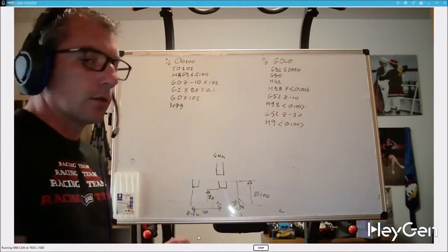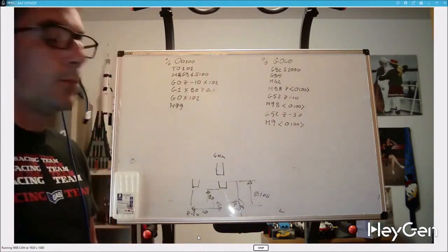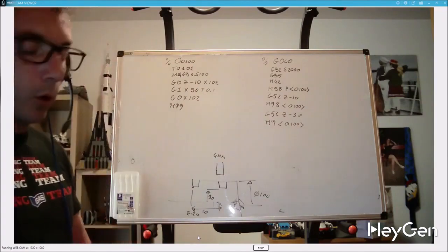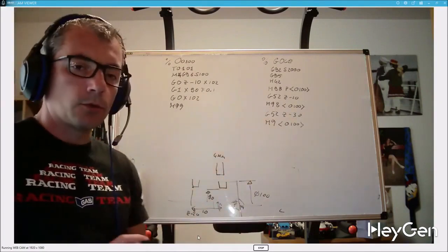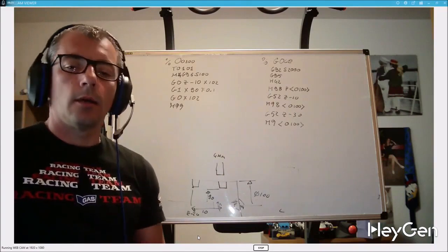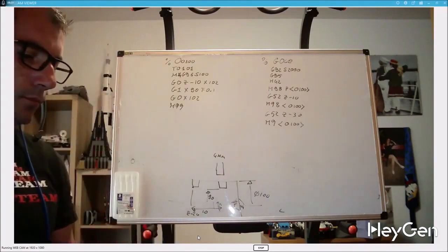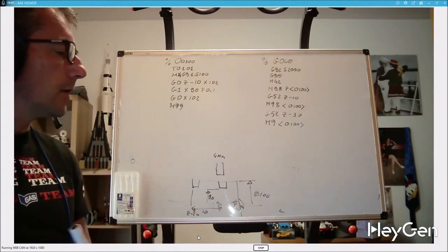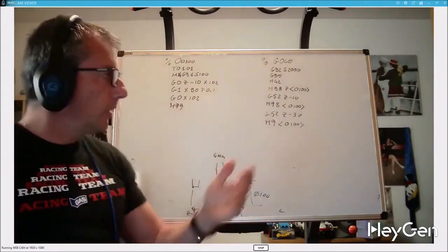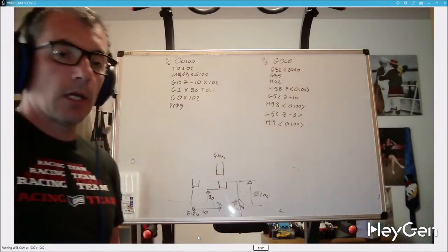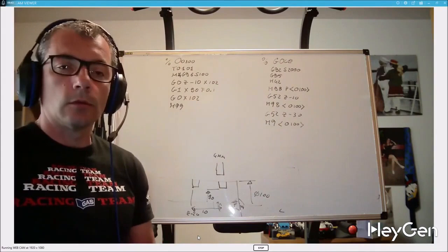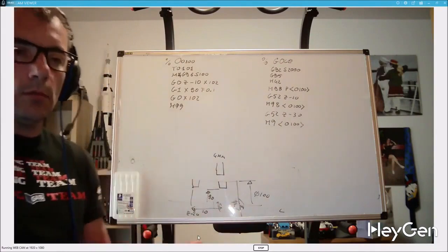The more attentive ones might say, wow, but there are other ways. There are conditional jumps. The luckier ones might have G10, which is an optional parameter that allows, at least on some machines, to repeat the cycle multiple times. I can create unconditional choices with parameters or calculations. All this stuff in 3 lines. Yes, it's true. This is one way, a simple way, an easy way to repeat a subprogram as I need it, and I use it a lot. It's not the only way, just so you know. It's one of many other things.